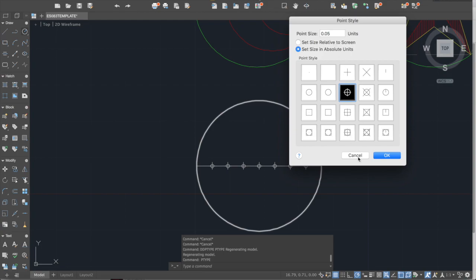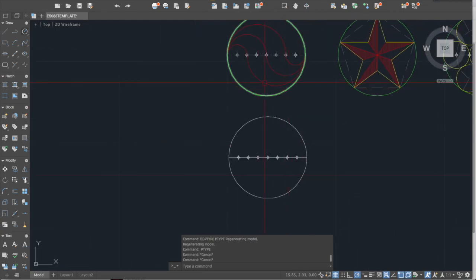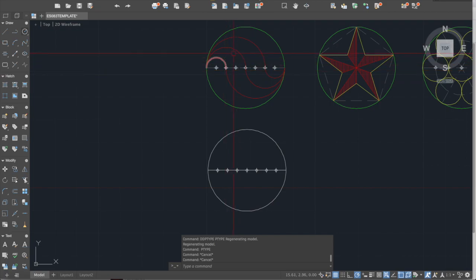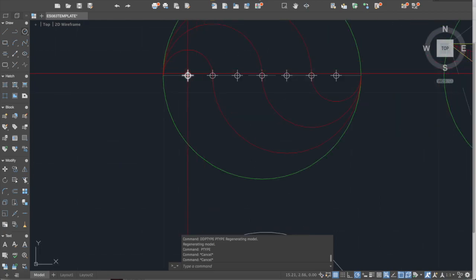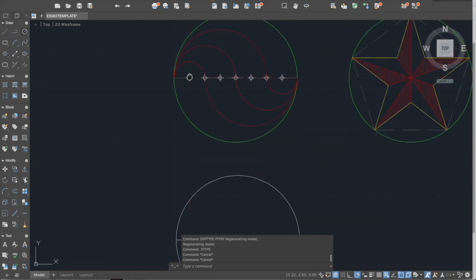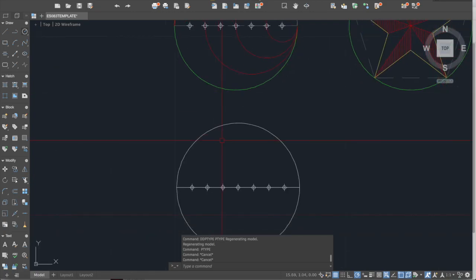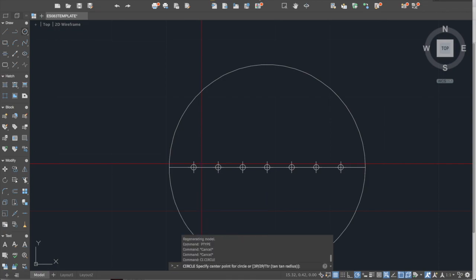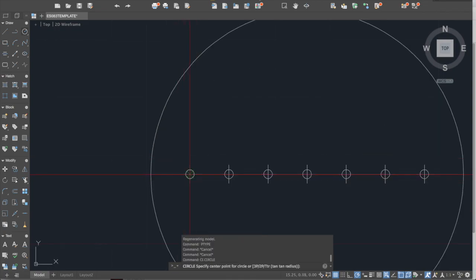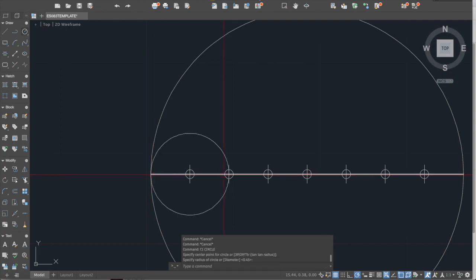Okay. So to continue, we have here 3 semicircles inside. So the first circle will be using the first point. So this is the first point of the first semicircle. So what we will just do is to create a circle, and then we will use the first midpoint, click this one, and then its endpoint will be the same endpoint of this big circle, which is this one. So that is the first one.